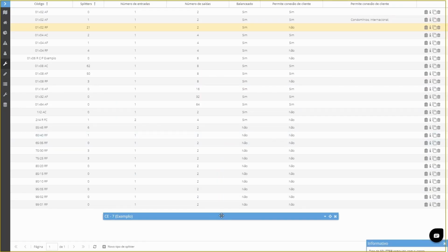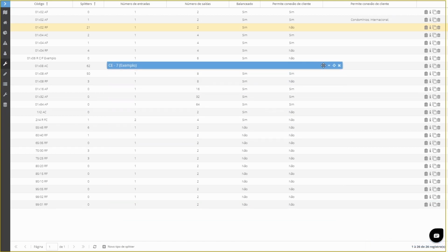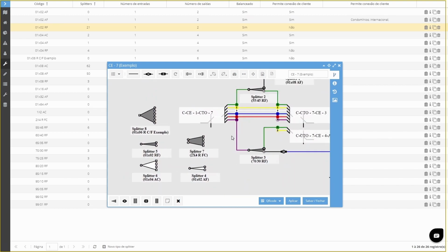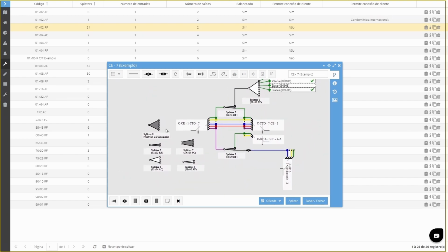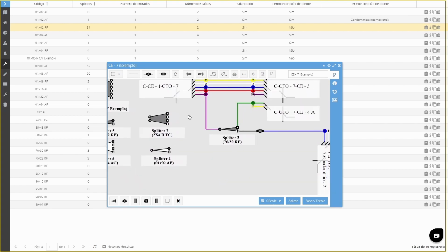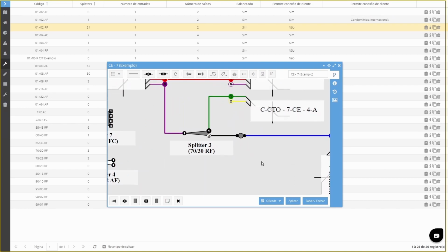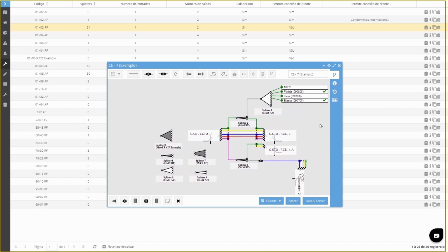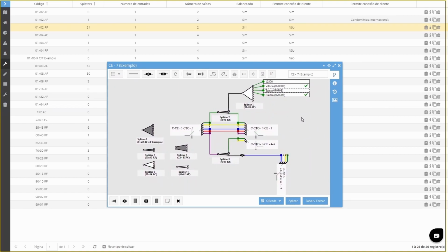As I said before, the splitter's inputs and outputs are already marked with these little balls or squares, which mean that they have fusers or connectors. So they come automatically on the fibers. You don't need to put a fuser or connector on each one, but you can also do it this way. In this splitter here, for example, a fuser has only been added to this output. The difference is that the attenuation setting for this output will be different from the set attenuation. So they'll stay here on the other outputs, and you can use this in any way that's useful to you. This is just an example.